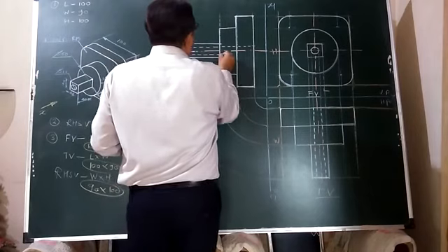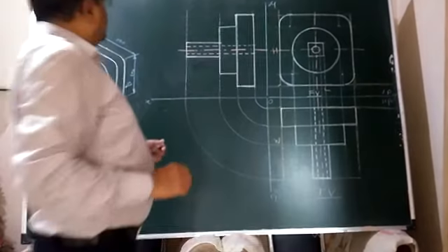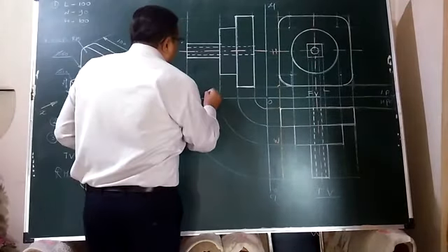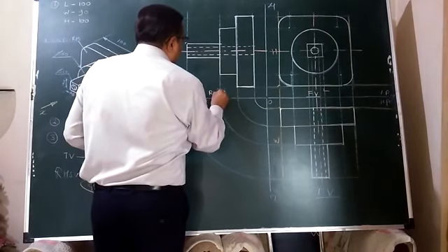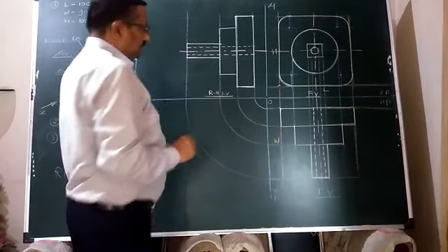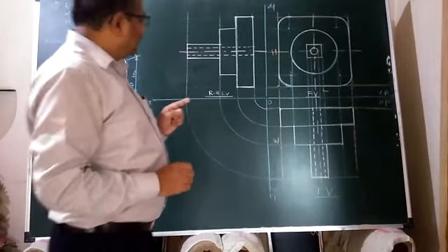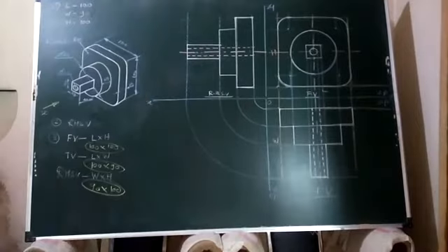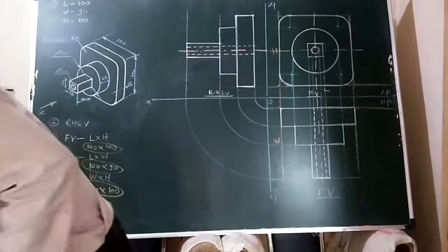Left to right you have to show dash medium thick lines, so that now the entire side view also has been finished here. Okay, so this is nothing but right hand side view image which is drawn on left of the front view. RHS, front view, top view and right hand side image. Okay, now leftover part is its dimensioning. Now we will finish that task also.